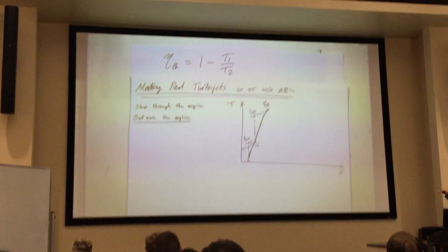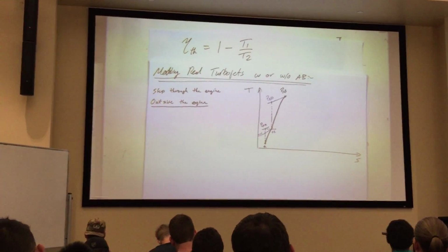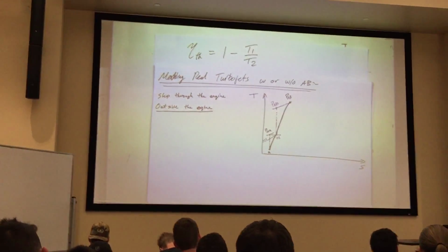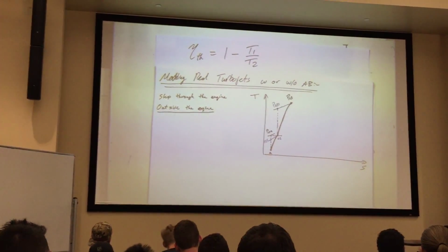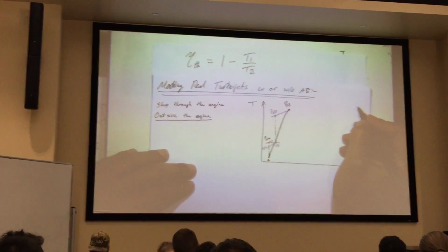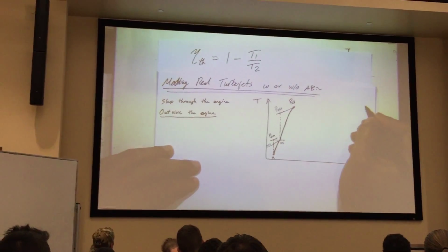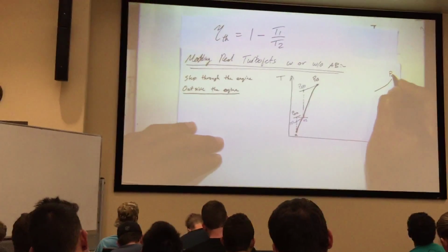Now, ideally, through my combustor, so this is PO3 actually. Ideally, through my combustor, I have constant pressure combustion, meaning I'm going to use this ignition pressure and ride it all across. But that's not what happens. I have pressure losses through my combustor due to flame holder drag and things like that you've done for problem 2 in midterm 1. So most likely I'm at a different pressure level. That pressure level is going to be somewhere out there. It's going to be less than PO3, so I'm going to name it PO4.